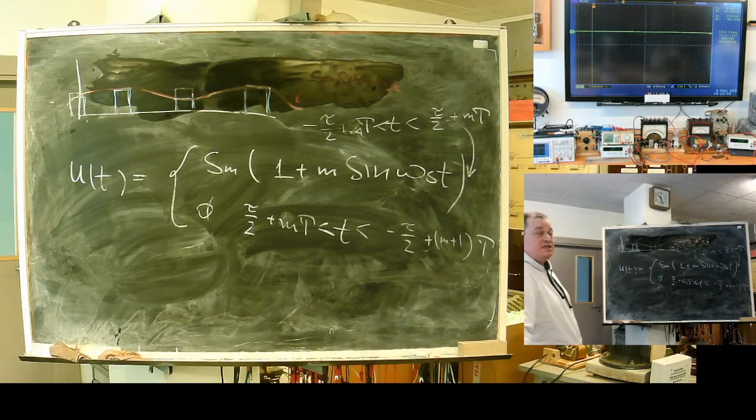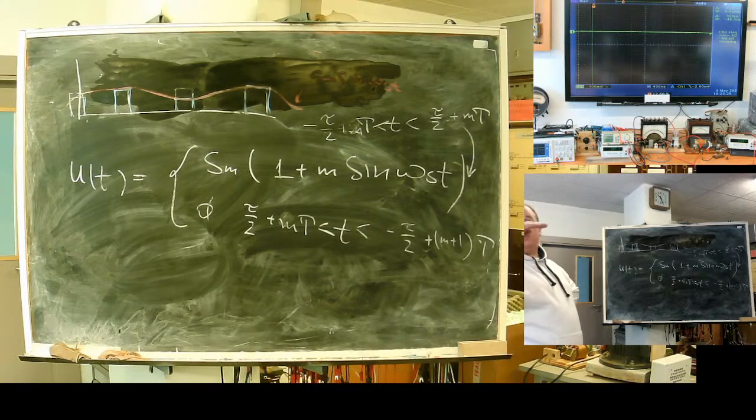When you need to deal with wide range signals, like a power system from normal mode to fault, 40 times, common analog to digital converters don't have sufficient range, and schematics include a prescaling device, like 1 to 1, 1/4, let's say 1/16 controlled divider. After the prescaling unit, you may see an amplitude modulated signal.